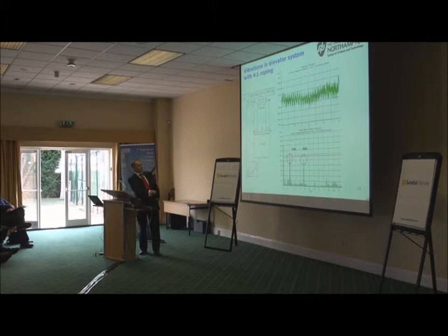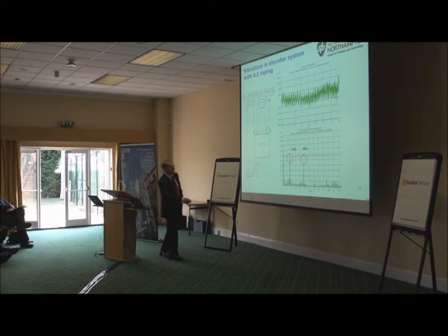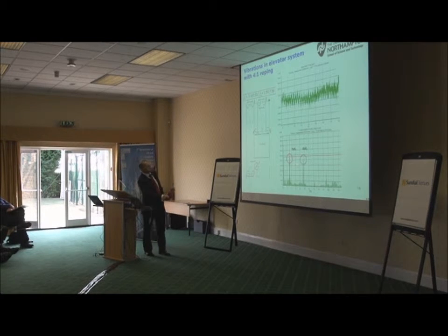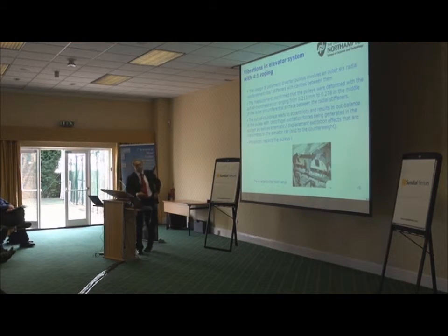So this is the frequency. We look at this point, this frequency, 3.2, and this is 6 times F2, the frequency of these pulleys. And that's what's shown on the spectrum. Now what do we do next? When you have those, we confirm through calculations and experimental tests, and we are able to pinpoint the problem.